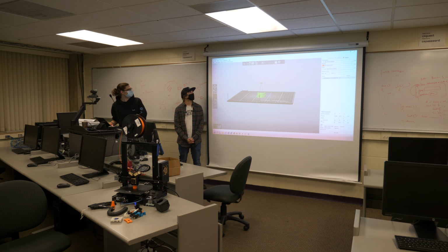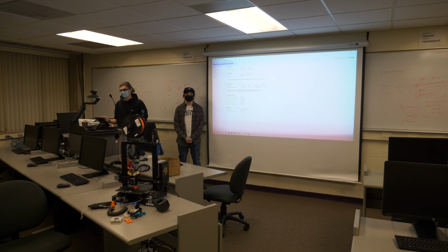In addition, there are parameters and a whole bunch of settings. You can very minutely play with the settings of your printer. You can change the temperature of a variety of different things, including the nozzle and the bed. This is all obviously specifically for FDM printers. You can change wall thickness, extrusion speed, rate of movement of the printer itself. Anything with a motor and a sensor, which is most of the printer, you can play with and change in this for filament and printer and everything like that.